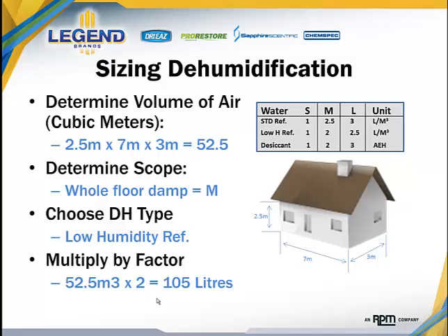However, if we're drying a bedroom, a hallway, and an adjacent bathroom, regardless of the percentage of those areas that are affected, if all of those spaces will be open to one another, then we must calculate for the total air volume in all of those spaces, because the dehumidifier must treat all of that air.